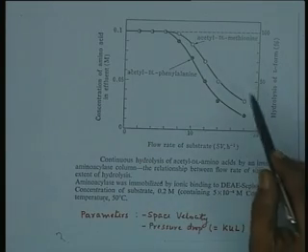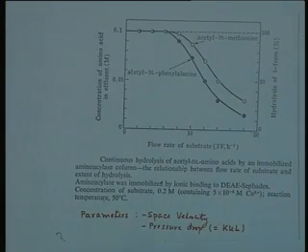And now another parameter which they considered was the pressure drop. Probably they considered it to find out the height of the column, and they noted also that the pressure drop across a column bed followed the typical fluid dynamic expressions which are available, and it was proportional to the space velocity as well as to the height of the column. And essentially they selected the height of the column based on the pressure drop limitations, so that they do not have to face very severe pressure drops. Particle size was chosen according to that.